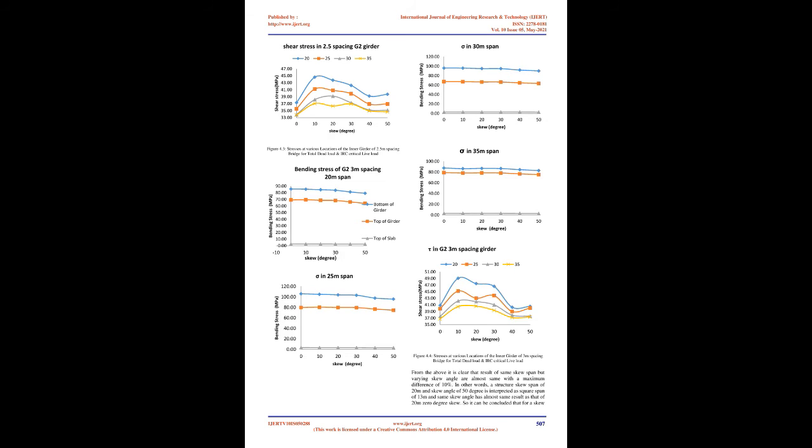End diaphragms are provided at the supports with minimum thickness, and the material for the end diaphragms and the cross bracings is taken to be the same as that for the webs. Table 1. Analyzed cases. 3.2 Loading conditions. Bridge dead loads and live loads as per IRC specifications are being considered in this study.